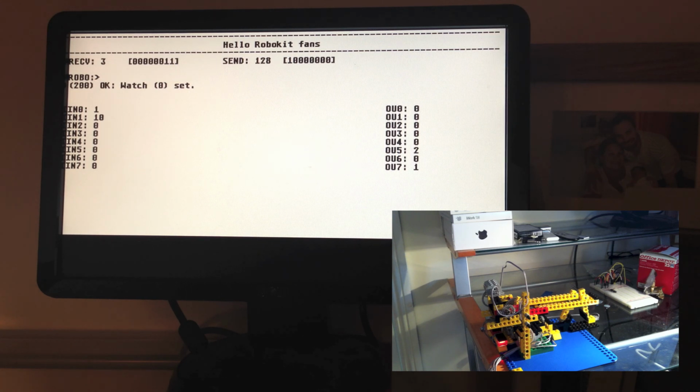Okay. Now what I might want to do, for example, is I might want to say I want to set a particular output until I've seen a particular number of pulses on an input channel. So let's reinitialize my input channels again. And now what I'm going to do is I'm going to say set 16 until 1, so this input channel 1 equals 10. Okay, I'll press return. So now it's counting up input 1, and then when that reaches 10 it should stop.